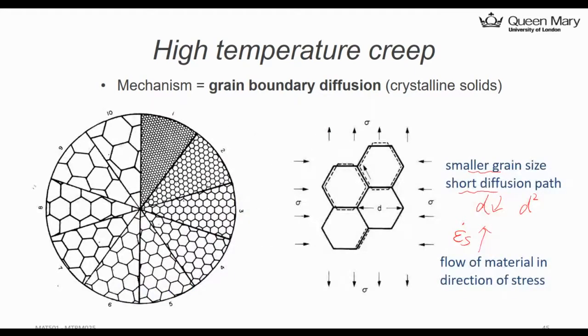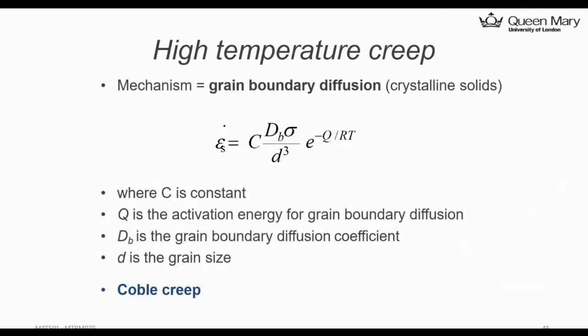And for the grain boundary, actually I want to correct myself, that's not right. For the grain boundary diffusion, the equation is even quicker because you have another thing kicking in, which is the gap. The gap between two grains can be related to the grain size, if you consider a limited material.